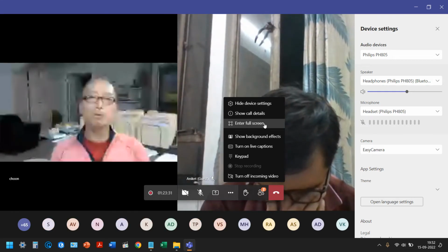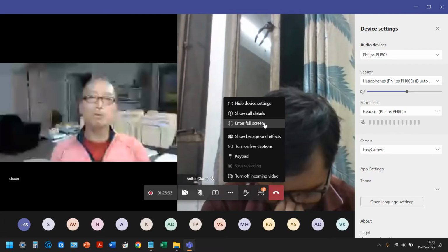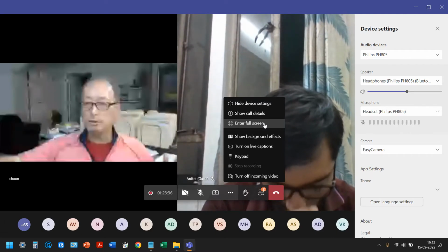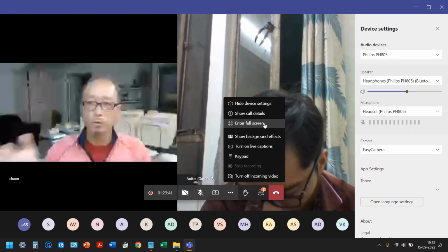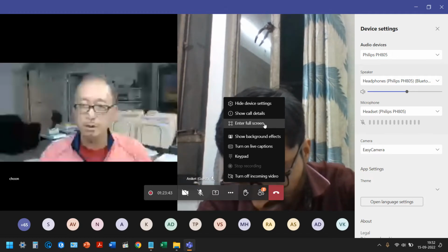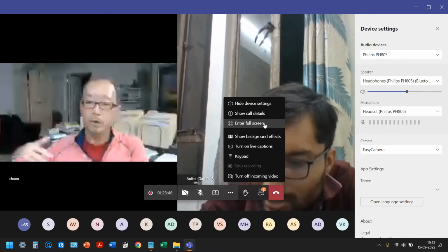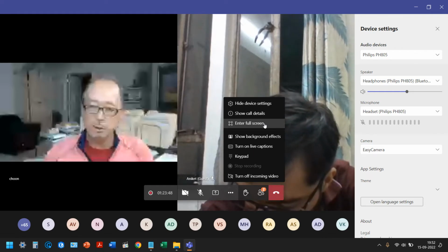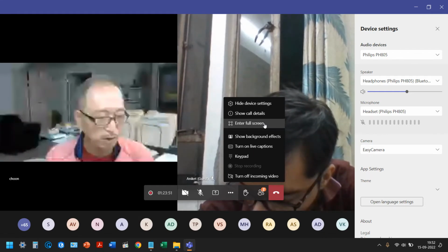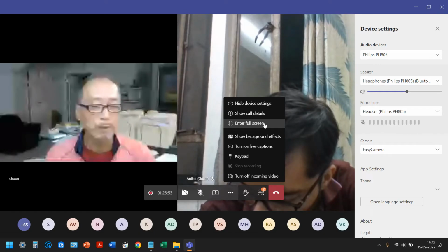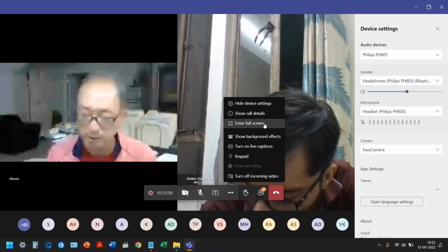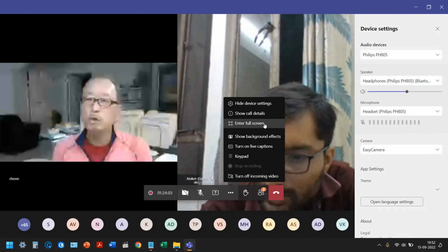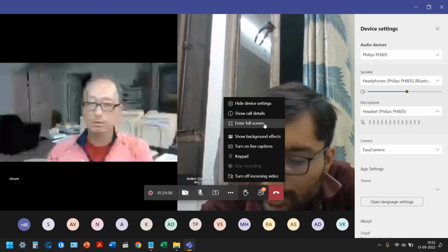But if you expect there is not much horizontal variation, then you can increase that interval to multiple receiver spacings. So sometimes if I see there is not much bedrock variation or not much stiffness variation within the soil, then I usually move by multiple, like 3 receiver spacings or sometimes 4 receiver spacings. So you will be able to move much faster to cover a long distance.